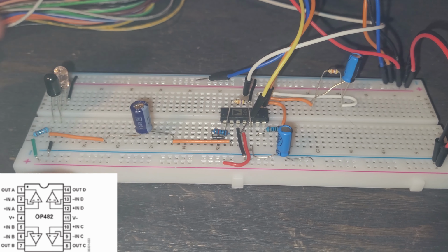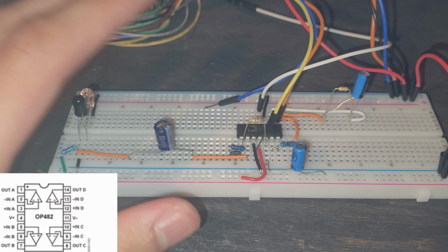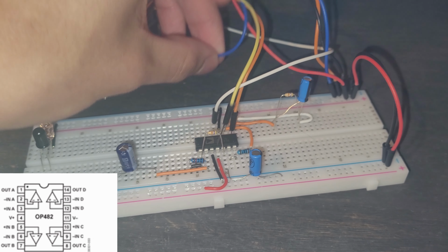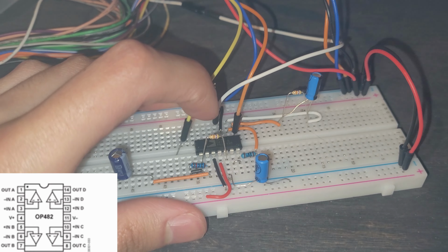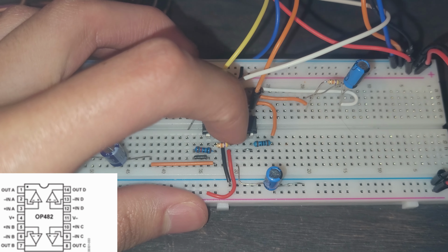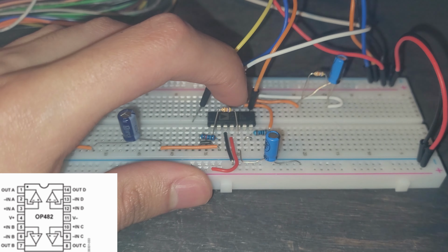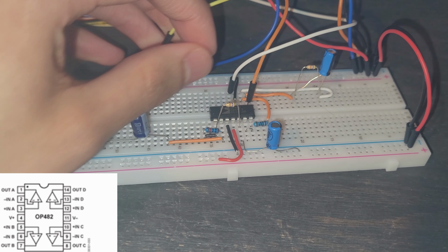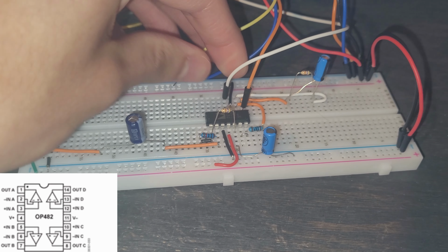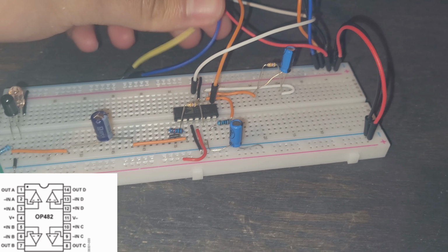We're now going to be looking back at the breadboard, and this is not just a picture because I think it's better served if we do it in person like this. So we can see that I've moved everything back. I have put this resistor back into the output of our kind of second stage, and that is here. We have this orange probe, and that's for the channel 1. We're going to be monitoring that output.